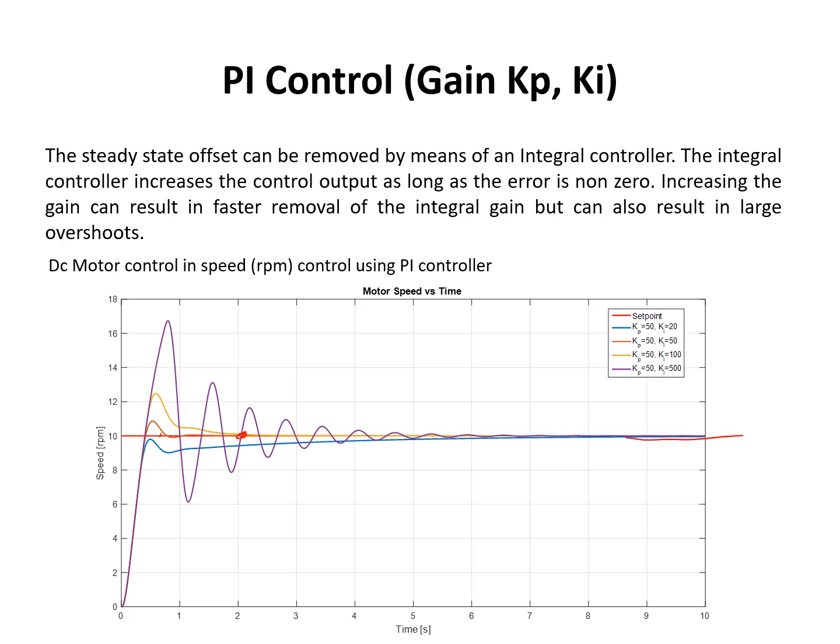There are ways you can circumvent it with additional added complexities to the PID controller. For example, you can switch on the integral term after a certain point. So in the startup phase, the integral error is 0, which reduces what we call wind up, and only at a certain point you switch it on. But again, that is much more complicated to do.